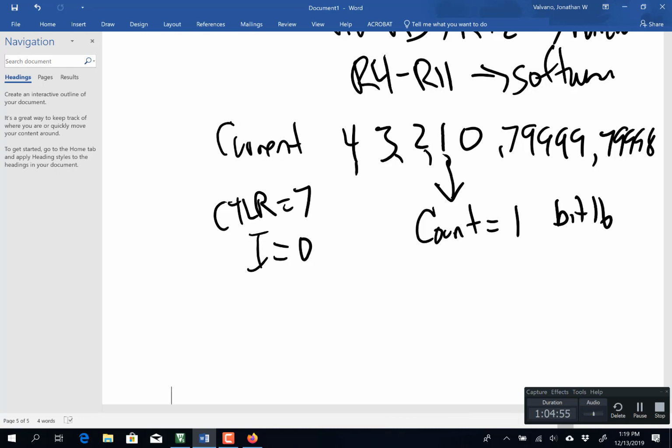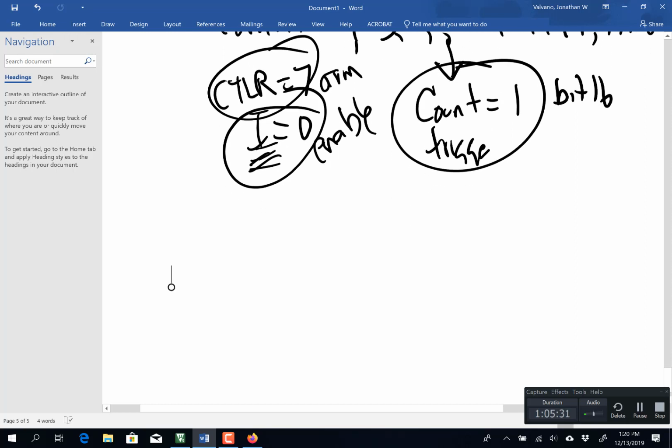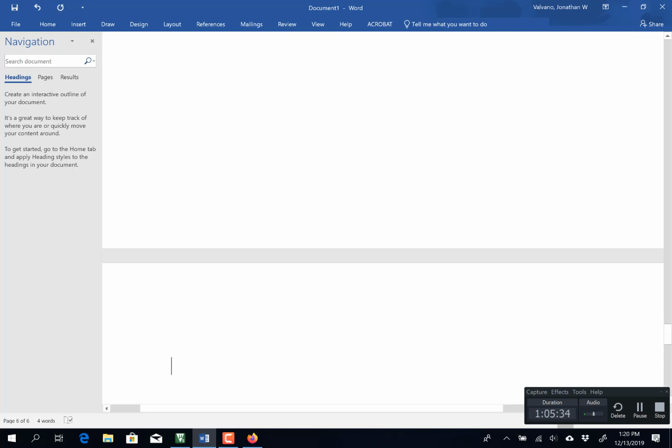Where's the I bit? What is I? The global interrupt mask bit. So 0 means it's unmasked. If these three conditions are true, it's armed, it's enabled, and it's triggered. Arm, enable, trigger. An interrupt will happen. Just will. That's the way it works. And what are the steps?